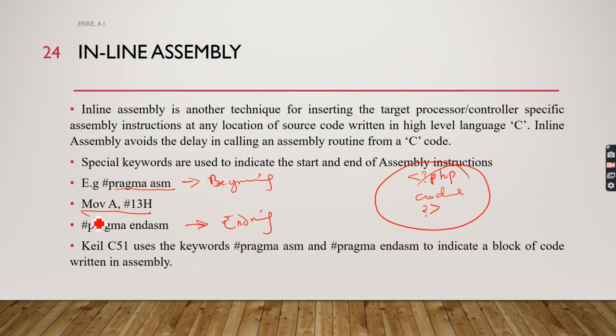Just like we say, this is the opcode and this is the operand, and this is moved into the accumulator register of the 8051. This data is in hex, because of the x hexadecimal value. Move it into the accumulator register.